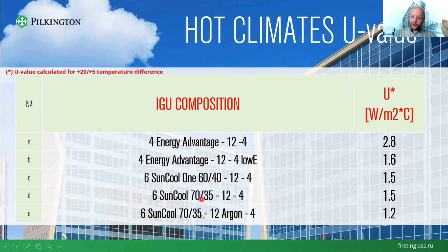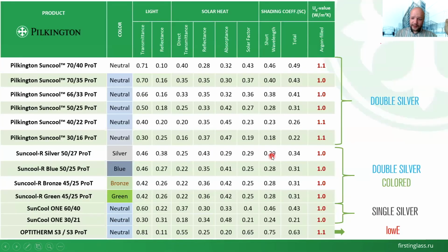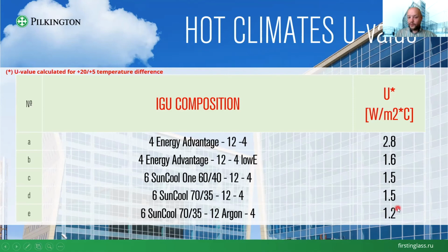For the hot climates, we are almost always using smaller spacers, but the smaller spacers give you a worse U value than the usual one. And when you look here, these values are given for the 16mm spacer filled with argon. When we're decreasing the spacer width, some of this U value goes away, unfortunately.